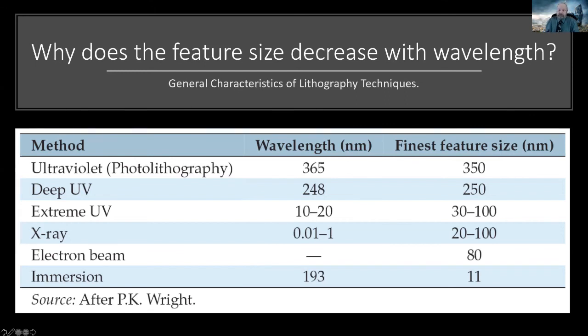You can't go into production making a computer chip and it takes you an hour for each one just to draw one pattern, and then you have to do 50 patterns to get the full chip. You know, that's not cost effective. Now, if you're doing research, and you're just wanting to make one little structure and test how it works, yeah, electron beam lithography is actually really good.